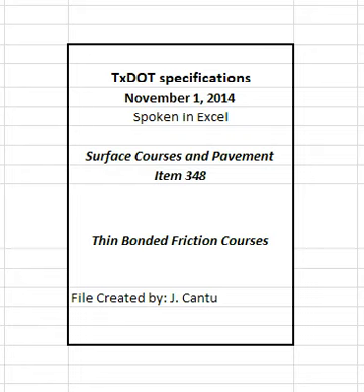Roll the freshly placed PFC with a steel-wheeled roller, operated in static mode, to seat the mixture without excessive breakage of the aggregate and to provide a smooth surface and uniform texture. Do not use pneumatic rollers. Moisten the roller drums thoroughly with a soap and water solution to prevent adhesion. Use only water or an approved release agent on rollers, tamps, and other compaction equipment unless otherwise directed.